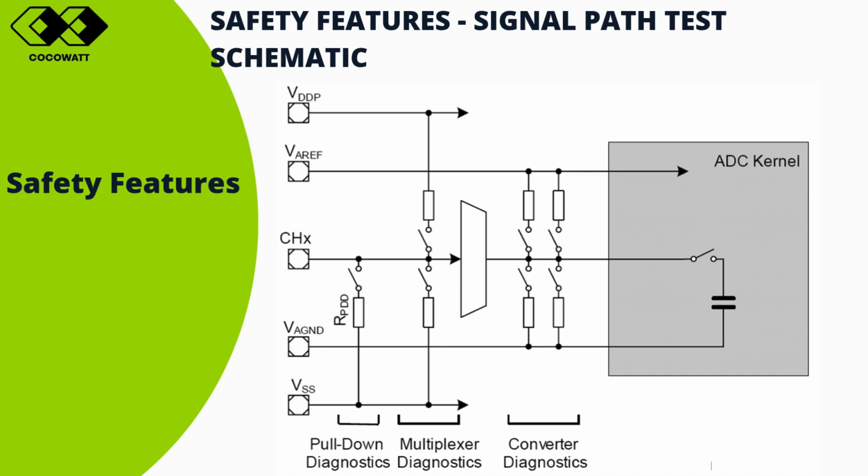Converter diagnostic. To test the proper operation of the converter itself, several signals can be connected to the converter input. Test signals can be connected to the converter's input either instead of the standard input signal or in parallel to the standard input signal.